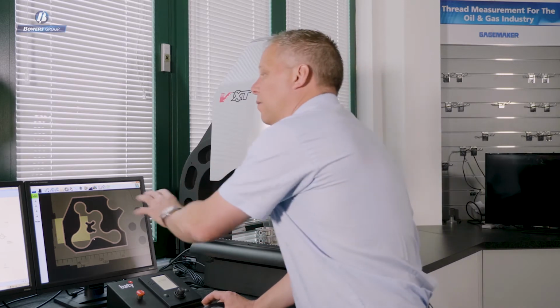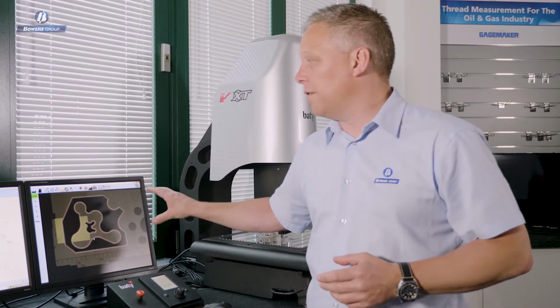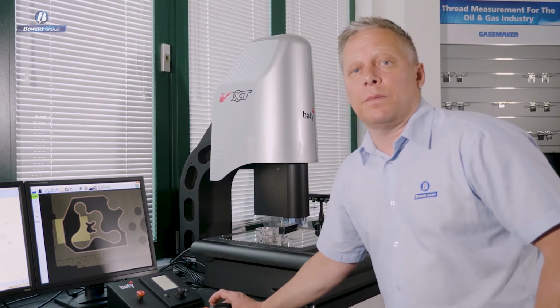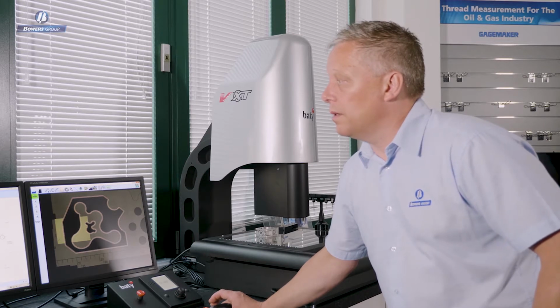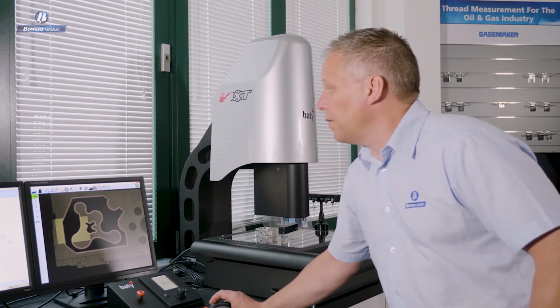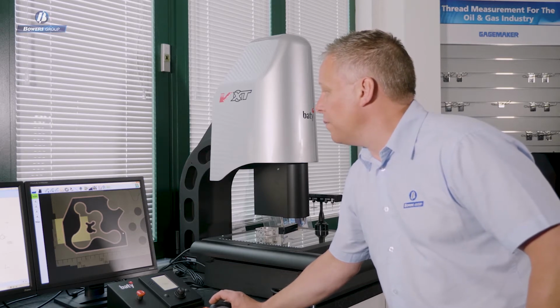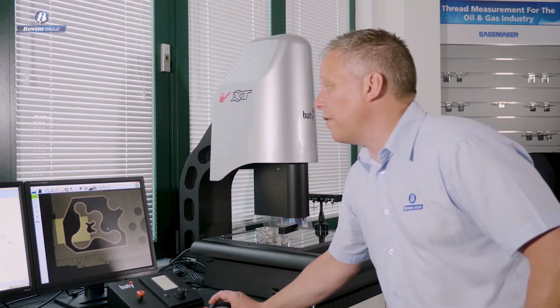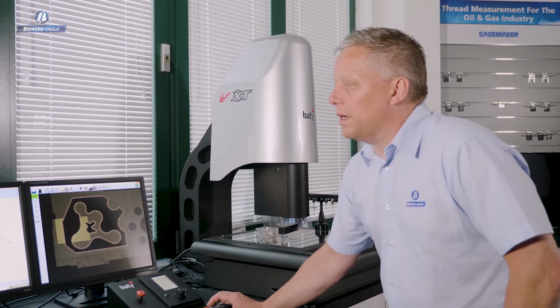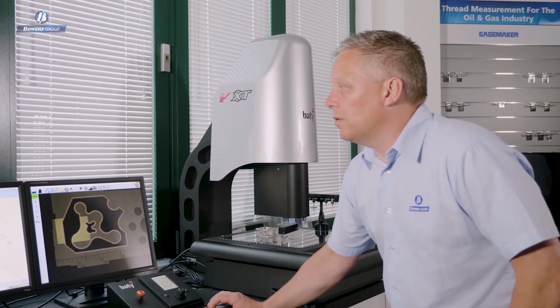So this is the view that we're used to seeing on a 500mm screen profile projector, and now for the first time we can actually replicate that on a camera-based vision system. So now we have a visual graphical display showing our scanned data points as green and in tolerance. We also have a visual overlay of the DXF placed over the top of the stitched image. So anything, even if we haven't measured the feature, we can still see where it appears in relation to the DXF. But the final thing that a software-based system like this can give you is an actual result.